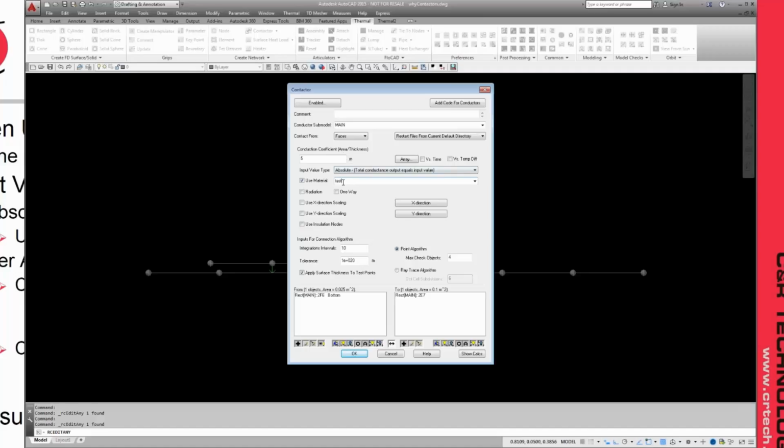So I've got my conductivity here. If I choose per area, it calculates the area, and all I have to do is provide the thickness through the material. And then if this is an edge, it even tells you thickness of contact area divided by length through the material. So this ends up being unitless.